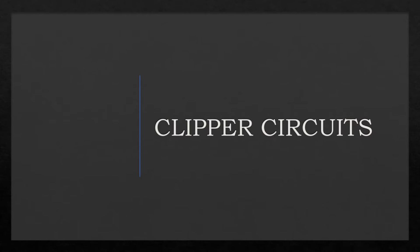Dear students, today is our 7th lecture, and in this lecture we will study the diode clipper circuits. These circuits are also called diode limiters. There are a variety of diode networks called clippers that have the ability to clip off a portion of the input signal without distorting the remaining part of the alternating waveform.